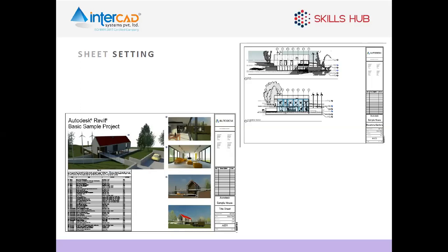Actually, the speciality of Revit is that while creating in CAD, it will be difficult to know whether it is possible to fit 1:100 on that paper. That we get with the print preview only. Here we can set the scale in the project browser itself, then drag it out, then we can identify whether it is possible, because sometimes at 1:100 we need to check if everything aligns in A2 paper and all. Okay, how to set the sheet setting, that is what we are going to learn next.